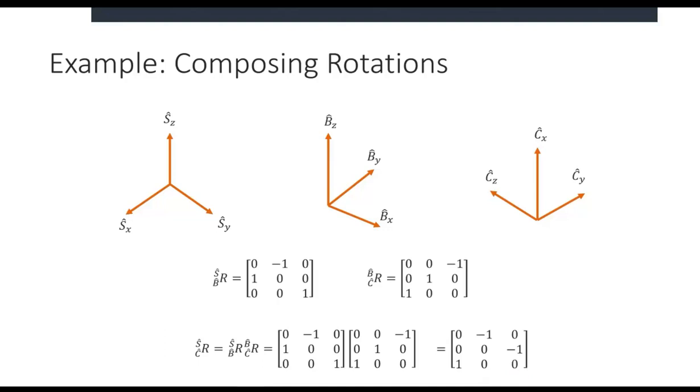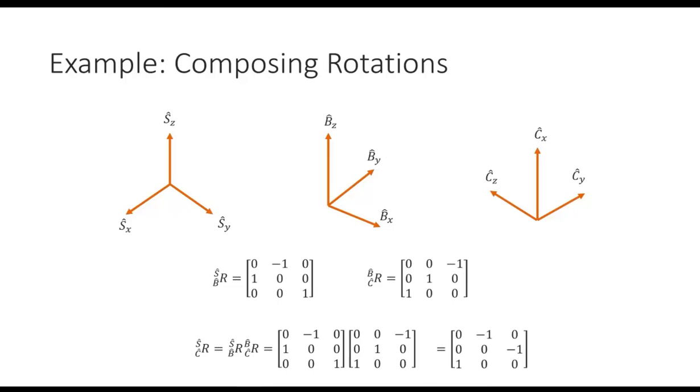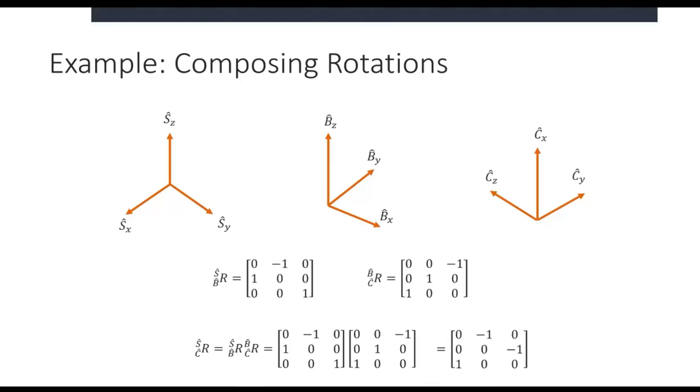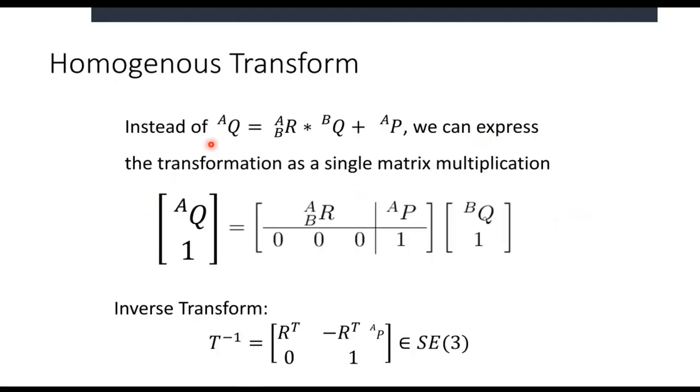Okay, so doing these rotation matrices is a bit mind-numbing, and it takes a little while to build an intuition about what's going on. The most valuable intuition you can have is this projection strategy of figuring out how much this vector applies to these other vectors that I'm trying to express this coordinate in. But when we use this, we also have to take into account that the origin might not be completely overlapping, as it is in the cases I'm showing you here. And so if we want to express points in a different frame of reference, we would normally write this out this way.